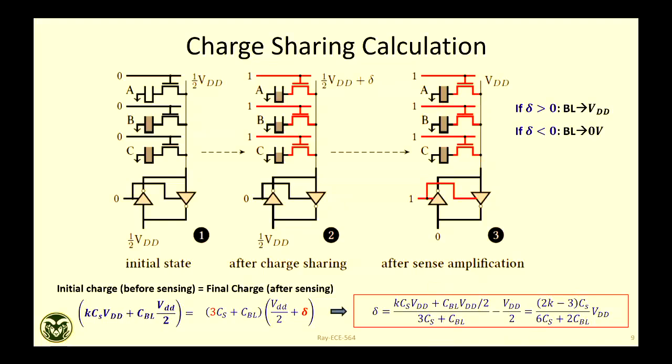Now, how will we implement this? What are the drawbacks of this framework? If you want to do computing using this triple row activation, what is the problem? Well, your computation will not always be correct because this depends on delta, right? Suppose these cells are discharging, because DRAM is a dynamic memory. Capacitors are always discharging. If they're not fully charged and you do computation after some time, you can come up with a wrong result. Because delta is anyway small, and here it will be even smaller because of all that charge sharing. That is one problem.